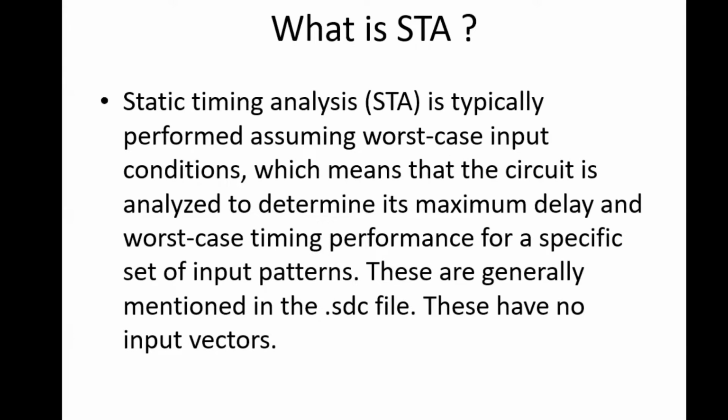Coming to static timing analysis, why are we doing static timing analysis, and what is it? Static timing analysis is performed based upon the worst case inputs. So what are these worst case inputs? Whenever we give the input delay high, the input delay is more. What does it mean? The input is taking more time to come to the flip flop or any combinational circuit or any logic inside my module.